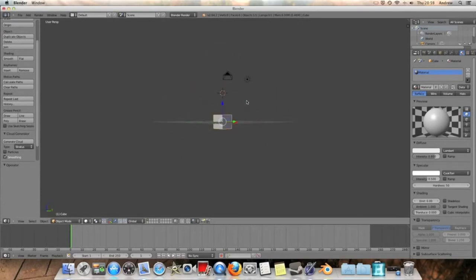And that's almost every number apart from 9, 0 and 5. And if I press 9 it doesn't actually do anything, it's the only one that doesn't do anything. But if I press 5 it's a little bit more confusing, because press 5 and it removes perspective. By removing perspective, I hope you can see the difference here. Obviously that's a bit more 3D like that than pressing 5 one more time to get rid of perspective. It's a lot more 3D than that is, and what that means is now when I press 1 we get a direct view, so that's like a flat square now.